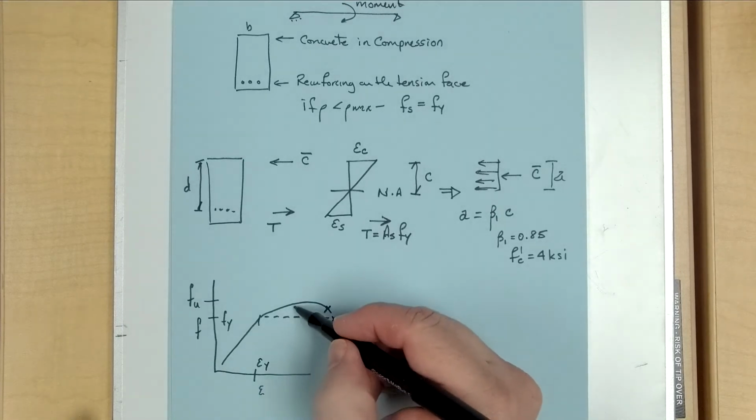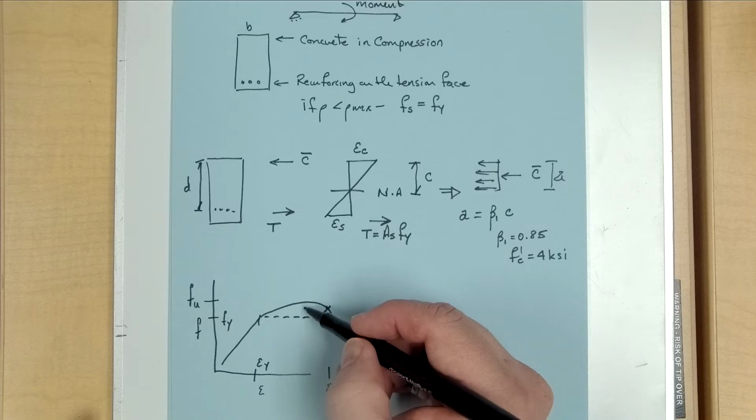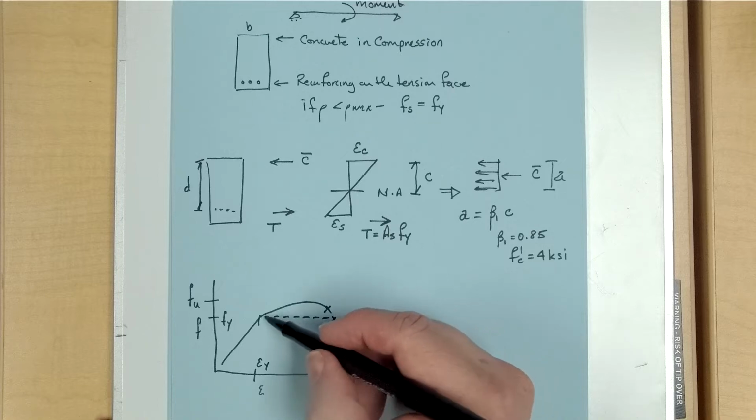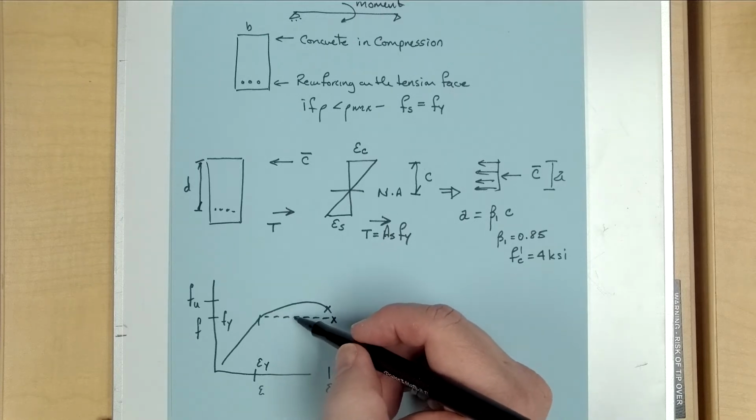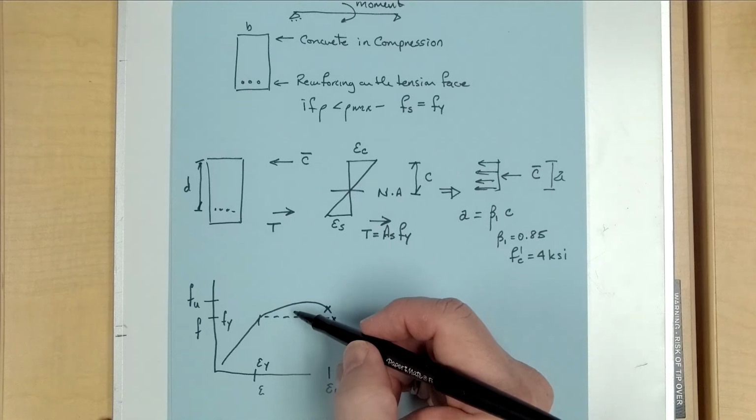And so we have this excess or reserve capacity. This is why the beam moves and keeps cracking, even though we have assumed it's F sub y. The steel is a little bit stronger as it plastically yields. And this is why we get multiple cracks and large deflections.